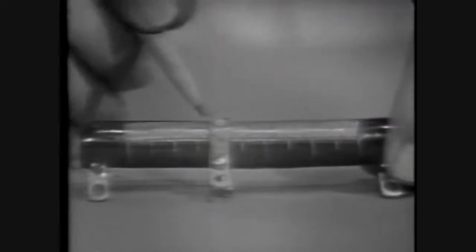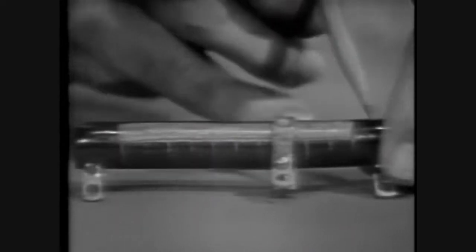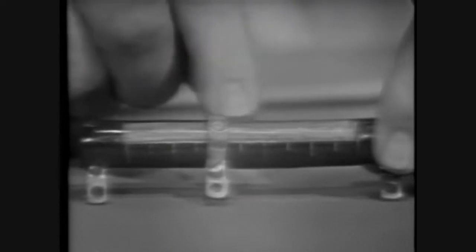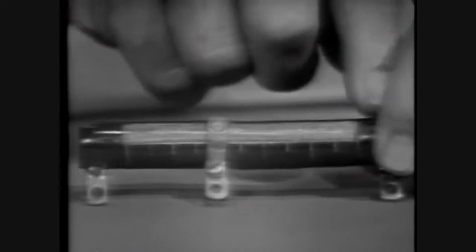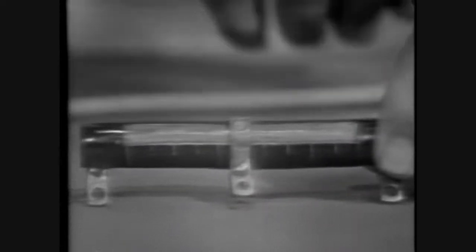Let's look then at some common resistor types. This one is a wire-wound fixed resistor with a variable sleeve. It's made of wire very similar to the wire that we used in the demonstration earlier. By moving this sleeve, we can change the length of the wire, say from this contact to this one, thereby changing the amount of resistance. As I slide the sleeve down, I increase the length of the wire, which means that I have changed the resistance from this terminal to this one. So by moving this, we would have a variable resistor, wire wound.